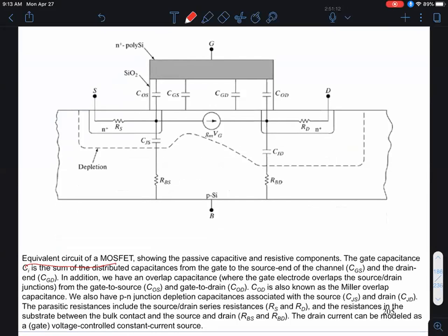But in practice, of course, we saw that there's a finite cut-in voltage corresponding to the junction potential. Plus, you have series resistance in the P and the N region and all that. And then in the diode, you also have capacitors because of the depletion capacitance. So that's the kind of philosophy behind equivalent circuits of all semiconductor devices.